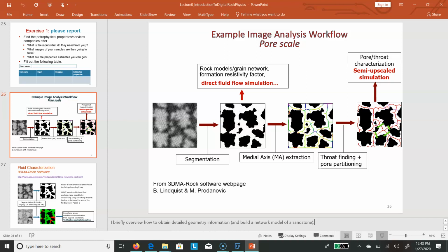Okay, and for a tube, I've been through my fluid mechanics class. I know what a flow through a tube is and what a flux through a tube is. And I can assemble all these tubes and how they connect. And at each pore, whatever comes in has to be what comes out. I know how conservation of mass works. Okay? And basically from that, I can actually speed up my simulation of transport through this porous medium.